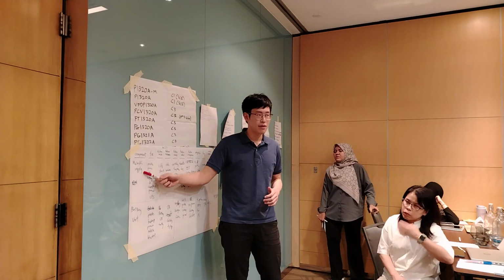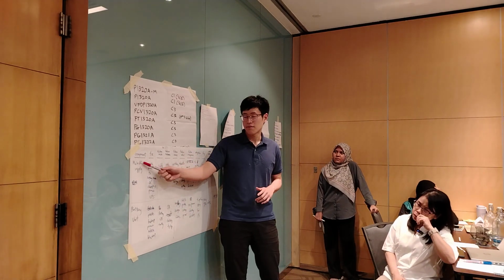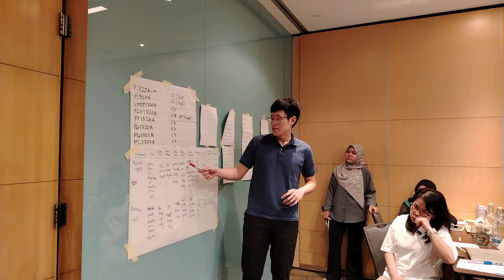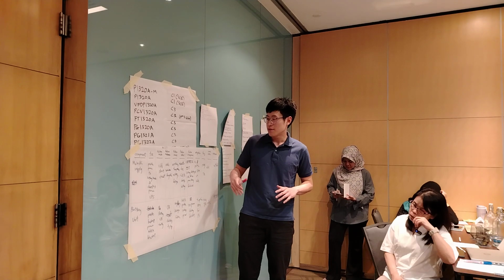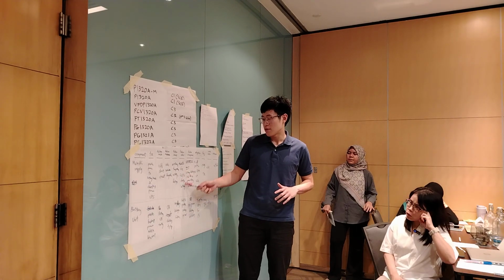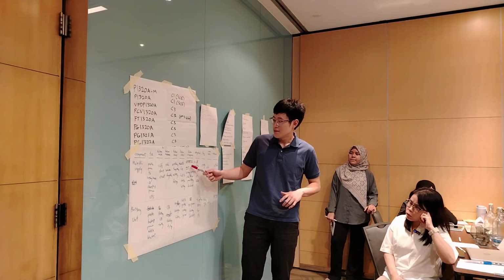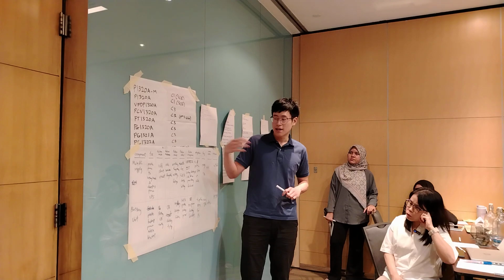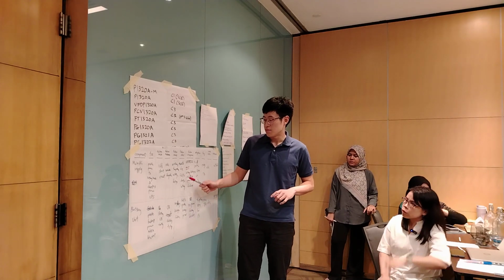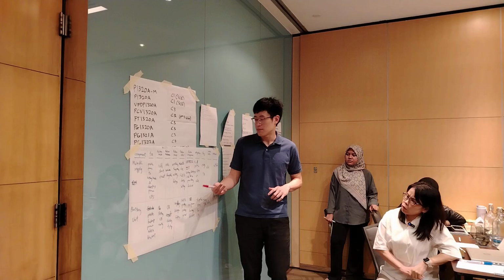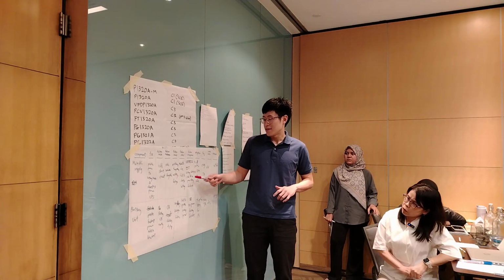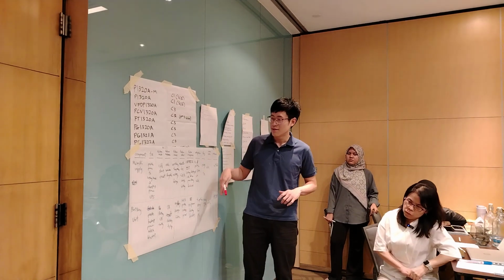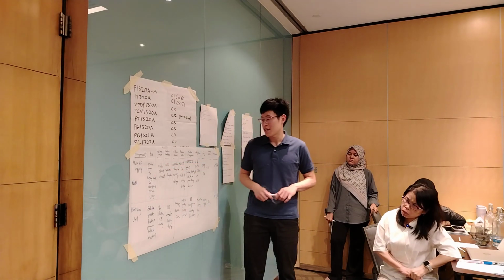Failure effect: what happens when the main AC supply fails? Basically, when the main AC supply fails, the plant is blackout and only the battery is supplying the power. We will have a blackout and also fail to charge the battery. Not necessarily the whole plant, just the power line of the UPS would have a blackout, and it will also fail to charge the battery. When the battery fails to be charged, it will discharge, and there are risks of no power supply during the blackout of the power line of that particular main AC supply.